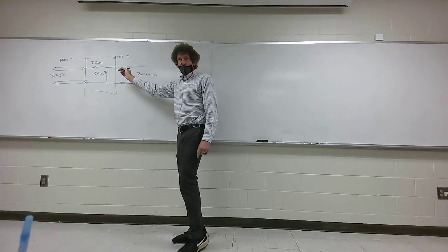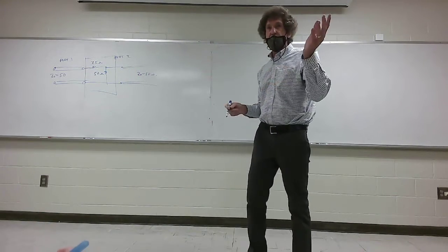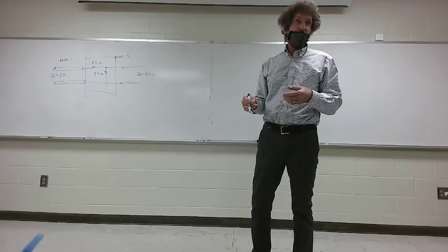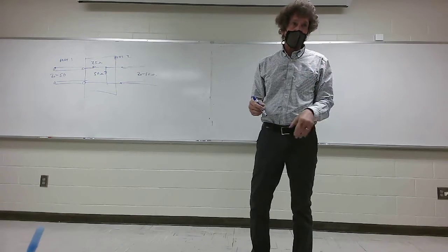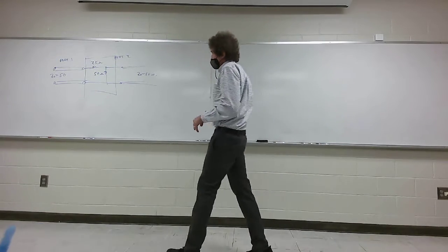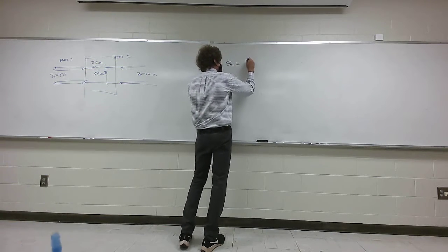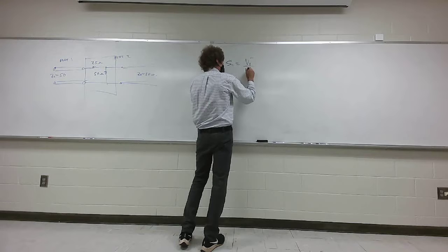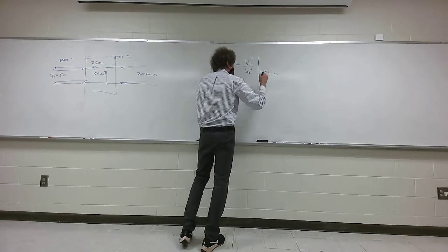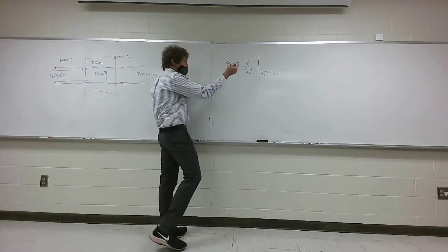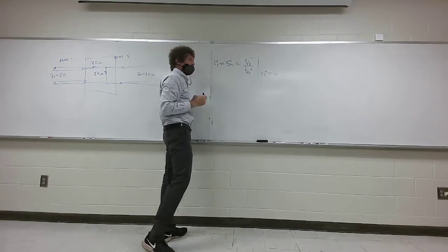Okay. Every time you do microwave engineering, you always make sure the load impedance is equal to the actual transmission line or waveguide impedance. If it's not, you've created a horrific problem for yourself. Okay, so for this one, I want S11 first. I know the definition says it's V1 minus over V1 plus, assuming V2 plus equals 0. That means it's terminated, or it's not going to have any reflections from the load, and that can be given as the reflection coefficient of port 1.